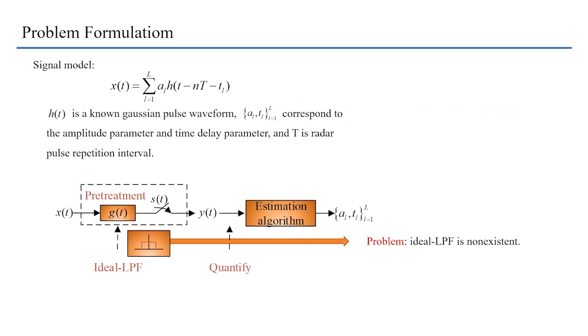With the classic FRI sampling system, which is shown in the figure, taking the basic sinc sampling kernel as an example, we modeled the process of FRI sampling and the reconstruction of the ground penetrating radar ultra-wideband Gaussian process.